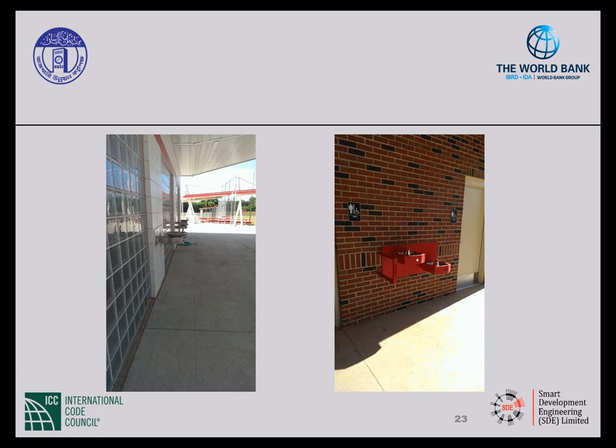On the right, you can see that the lower drinking fountain, the underneath side of that, is mounted at 580 millimeters above the pavement, so nothing additional is needed. But on the left, they've added a bracket with the lower edge at 580 millimeters, and this protects this drinking fountain from being a protruding object.